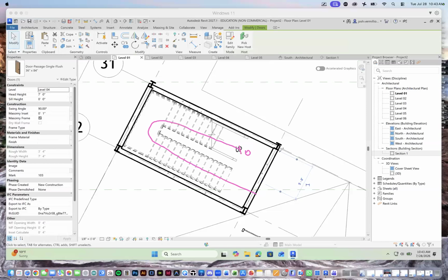And so again, in the spirit of making sure that this is opening in the direction of egress on the bottom floor, your door swings are going to swing out again, out of the way of the direction of egress. So they're going to swing outwards because people leaving the first floor aren't going to go up towards the second floor, they're going to leave the building. And so again, that just shows you how the fire stairs work, right? And hopefully the logic behind them.